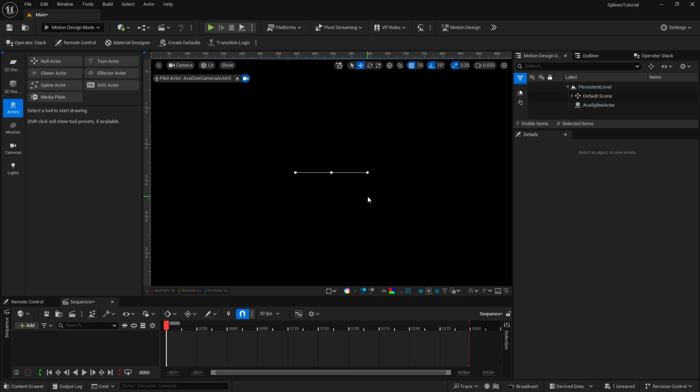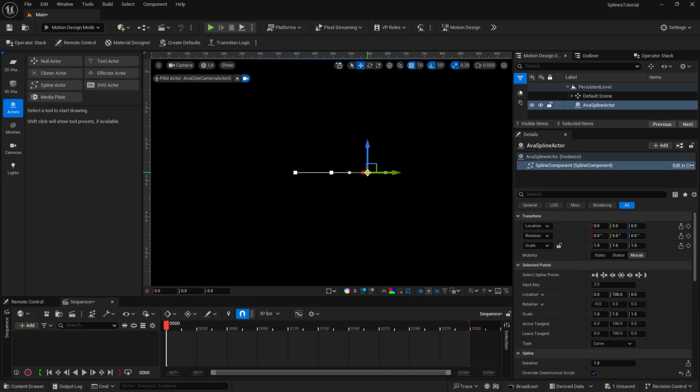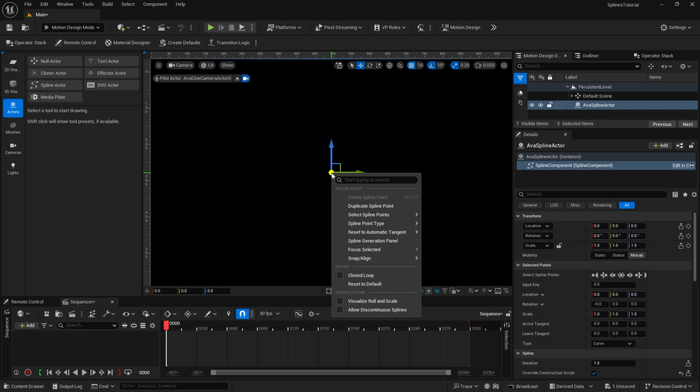After setting that third point in there, I'm going to delete these other 2 points. I'm going to select this end one here and then simply delete it, and then jump back over here to the left and delete that one. And I'm left with that 1 point. From there, I'm going to right click again, and we have all of these options that we can use to work with these points and the spline. We'll go over a lot of these throughout this tutorial.